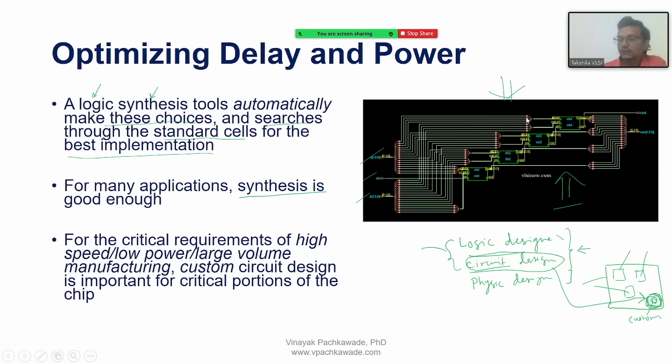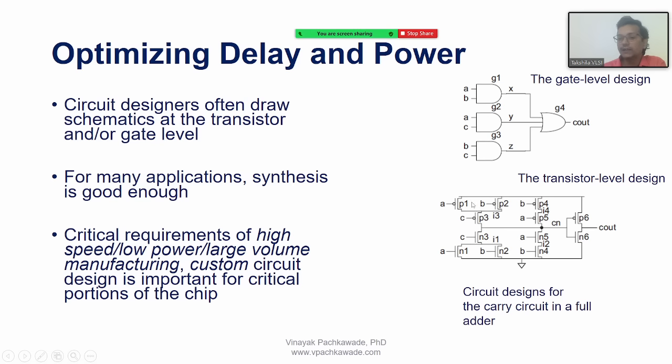In the same fashion, there will be circuit design IPs also already installed. So if it chooses a NAND IP or NOR IP, the circuit level implementation is also there inside that library. Accordingly, the tool will take those IPs for each gate, and then the interconnection will be done automatically.